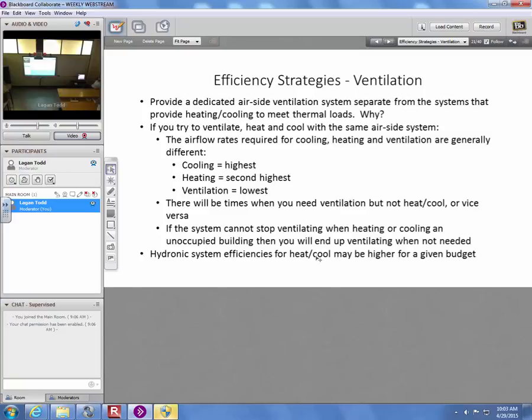So a hydronic system's obviously still going to have some sort of an air handler or an exchange? Not necessarily, right? A radiant floor or any kind of radiant-only system doesn't need an air handler. But you'd still have some kind of ventilation system. Yeah. But now you downsize your air side to one little tiny HRV or something like that, right? Interesting. So I'm hearing that you can't always hope to buy one unit that's going to do everything. You might have to buy several different components. Yeah, and try to coordinate them as best as possible.